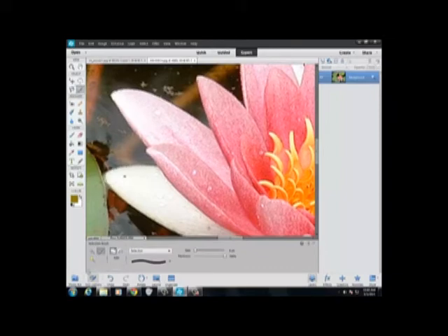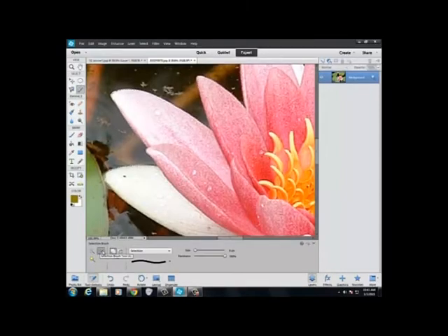Anytime you use those three tools, those are tools I like to call the easy select tools, because the computer does most of your work. It's kind of easy to use, but they don't do a good job. They don't do a finished work. So you're always going to want to come back to the selection brush and finish your work. Please notice the selection brush comes with an add to selection and a subtract from selection.